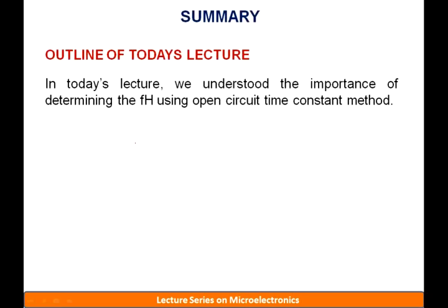Now to summarize, in today's lecture we understood the importance of determining the upper cutoff frequency using a unique technique known as the open circuit time constant method, and this method can be used to determine any amplifier's upper cutoff frequency with ease. Whenever we determine the upper cutoff frequency of any amplifier configuration, we include the overall resistances and capacitances present in the entire amplifier configuration. So this method is very well suited for the determination of the upper cutoff frequency.